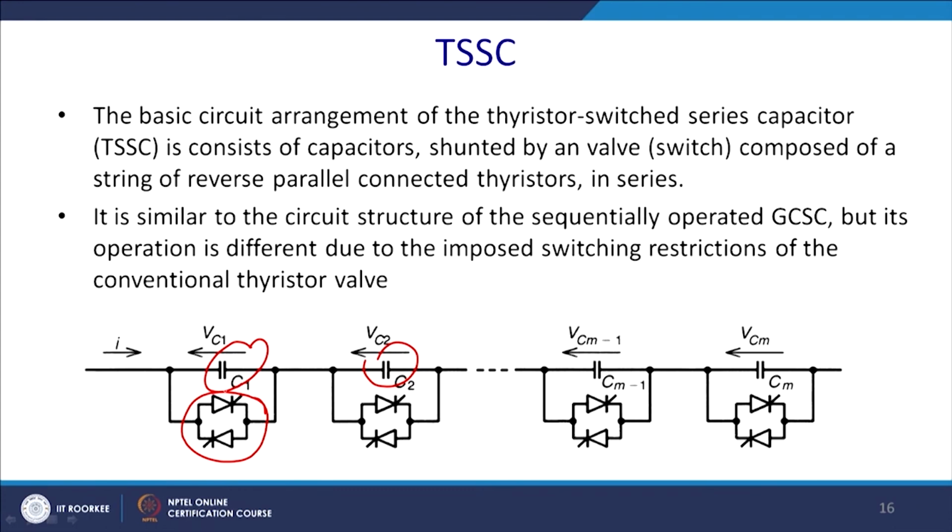If you do not trigger the thyristors, then the total capacitor will be injected into the system, and accordingly if you change the alpha triggering angle or the delay angle, then the value of the capacitor, and subsequently the voltage across it, will change. This is the way you inject different amounts of voltage VQ into the line voltage.